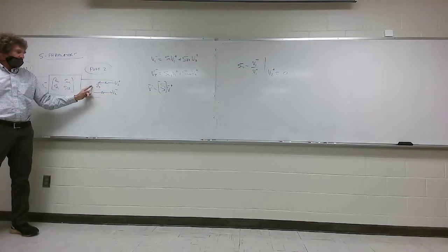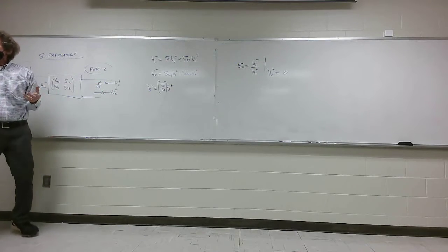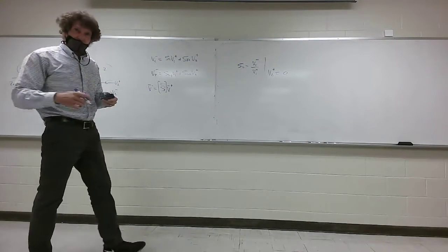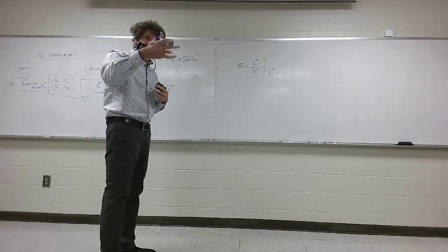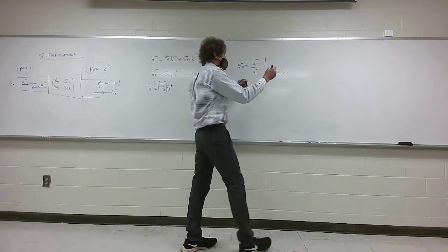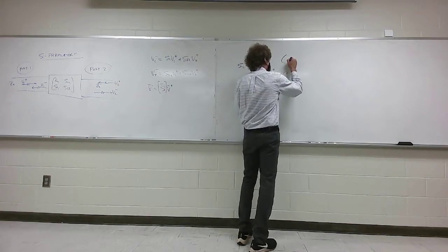If this is terminated into its characteristic impedance, the reflection coefficient is 0 at the load, and therefore there is no V2 plus. And you can put down here that port 2 is matched.